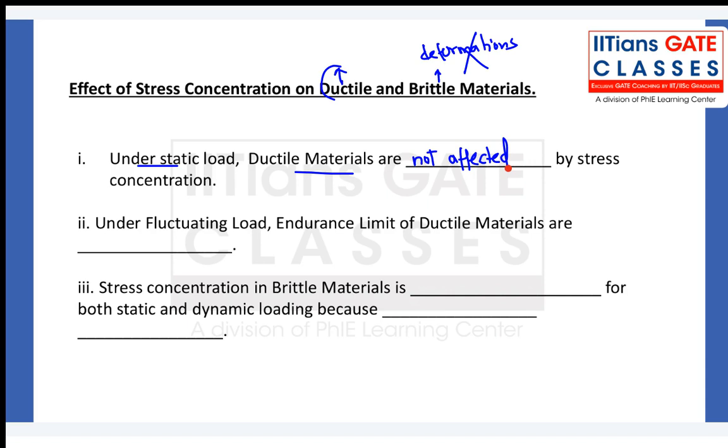There might be some stress concentration, but as we are applying force, if the material deforms, what will happen to the stress concentration? It will get dispersed. It will get broken, and it will move to different areas. And the stress concentration goes away, and that is why there is not much effect. We don't have much problem.